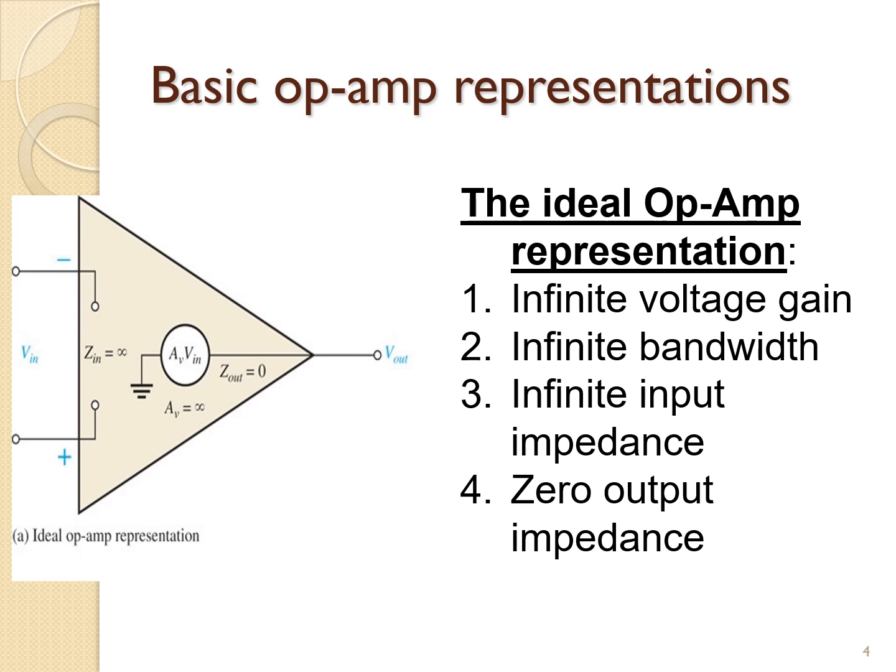To illustrate what an OpAmp is, let's consider its ideal characteristics. A practical OpAmp, of course, falls short of these ideal standards, but it is much easier to understand and analyze the device from an ideal point of view. First, the ideal OpAmp has infinite voltage gain and infinite bandwidth. Also, it has an infinite input impedance so that it does not load the driving source. Finally, it has a zero output impedance.